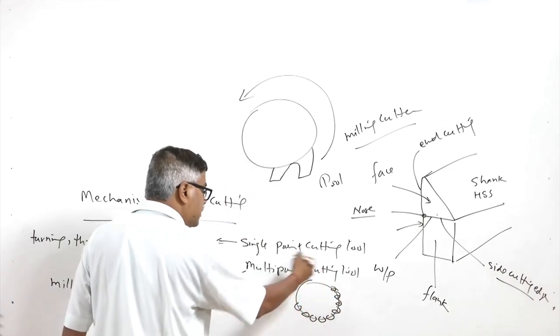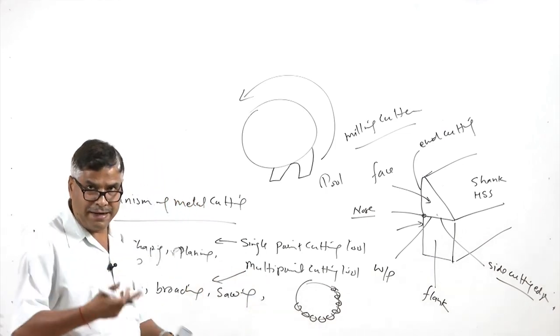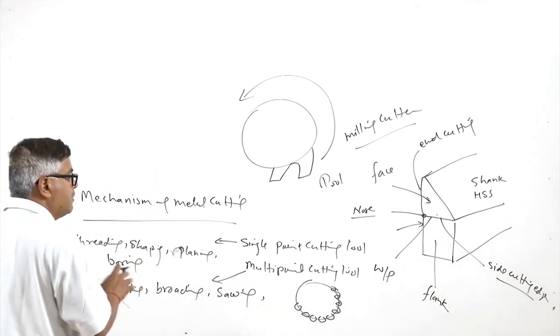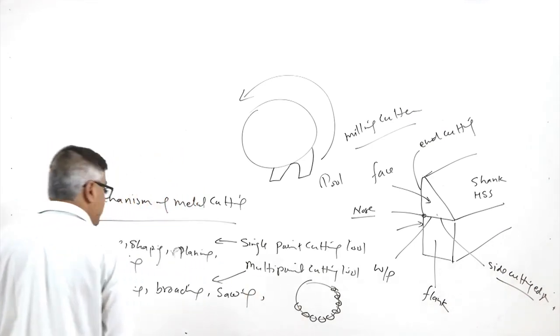These are also visually multiple points performing cutting, but the cutting edges are oriented in a random manner. So, there is no specific way by which the cutting edges perform the cutting in the grinding wheel.